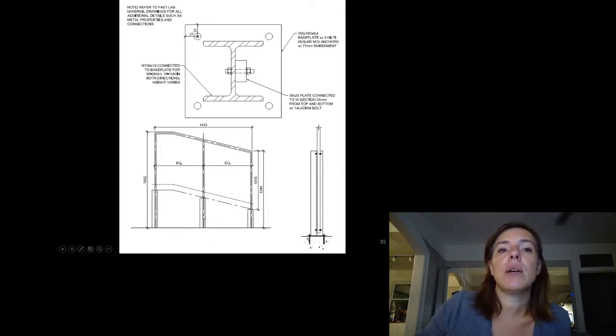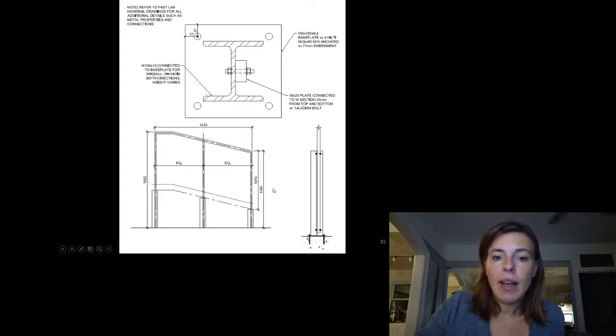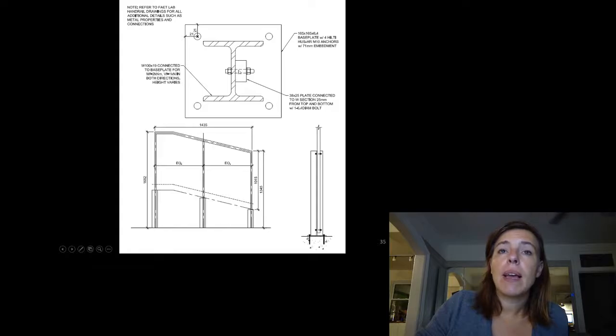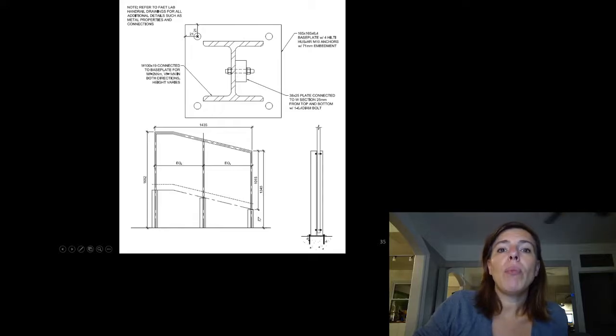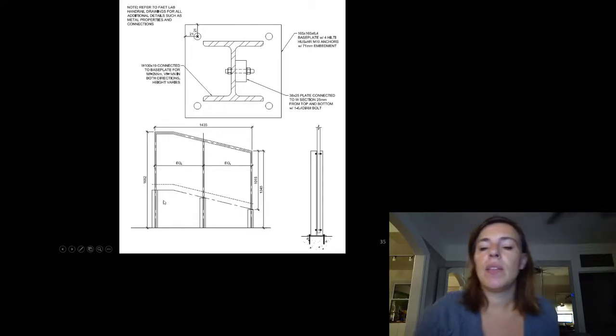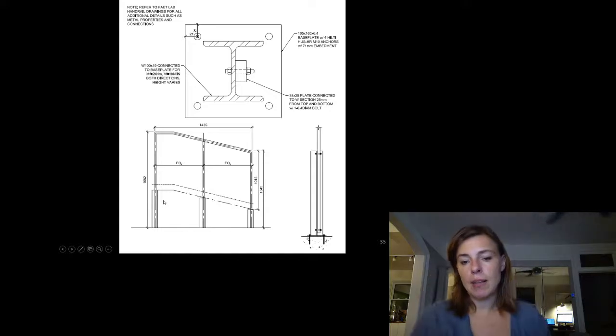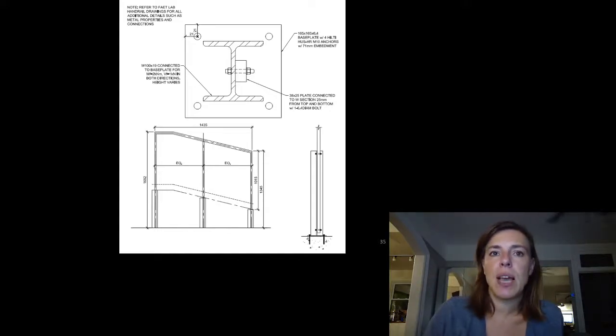So what I suggested was to build what they normally were going to. They had already fabricated this, in fact. And then I told them to provide a 100 by 19 HSS that's anchored down into the concrete slab down here. You can see that detail there. And then they came along and fastened their posts directly to that HSS. So it's almost like the guard only goes to here, and then we have really stiff, strong upstands picking up the guard, or this was actually a handrail at that point.